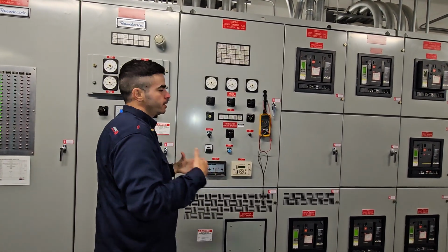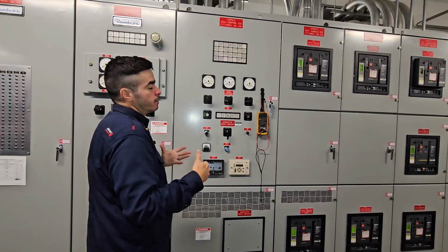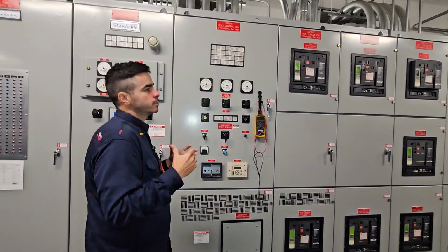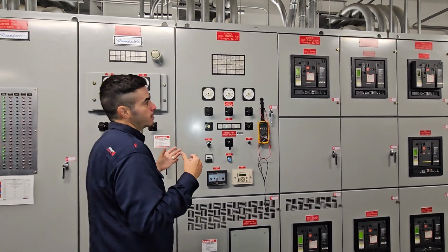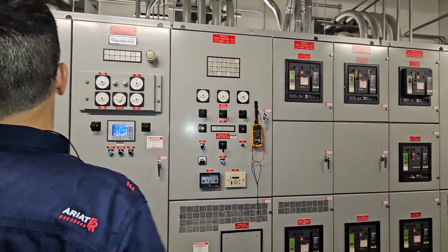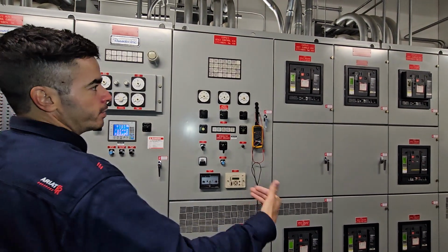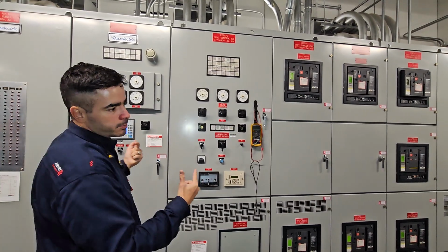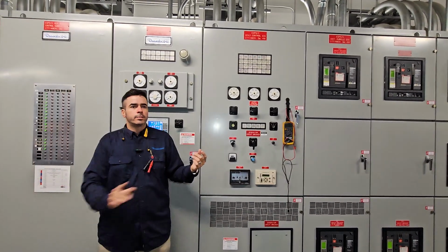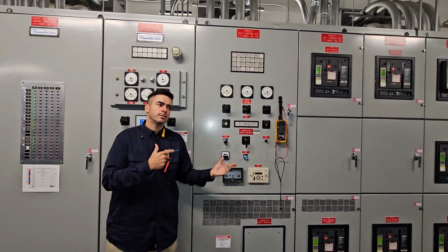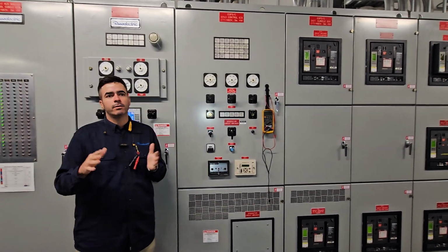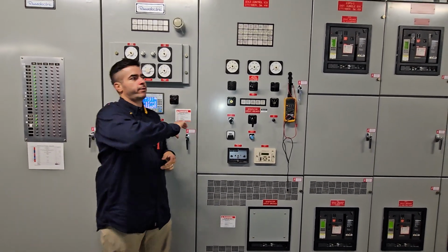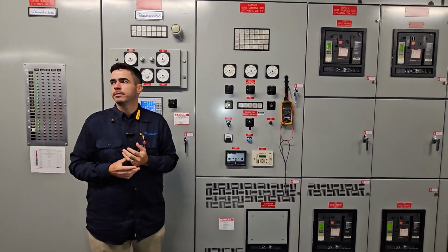And we might start getting alarms. One of the generators might shut down. So it's always important to know where to look when you start getting some funky things. You've got to look at the gauges and see, okay, kilowatts, they look good. Amperage: if there is no load connected, what amperage do I have going on? There is always some chance that we get some current circulation even if we don't have a load connected, just between the two generators. That is kind of normal if it's not over 5-10% of the capacity. But if we see like 500 amps with no load, there is a problem.